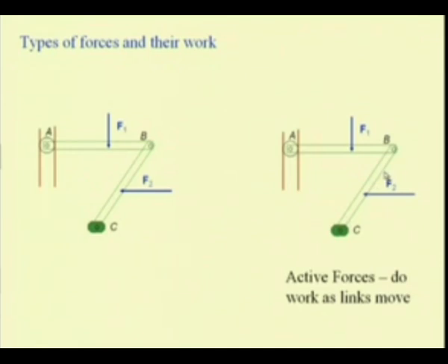That means the displacement should be consistent with the constraint that at C the position of this link cannot move, or this link CB can only rotate about this point C, and at A this point can only track along this dotted line. That means this roller is confined to the slide or the slots that is available.